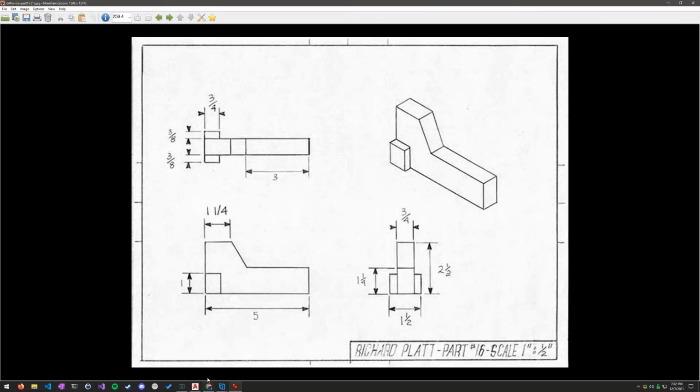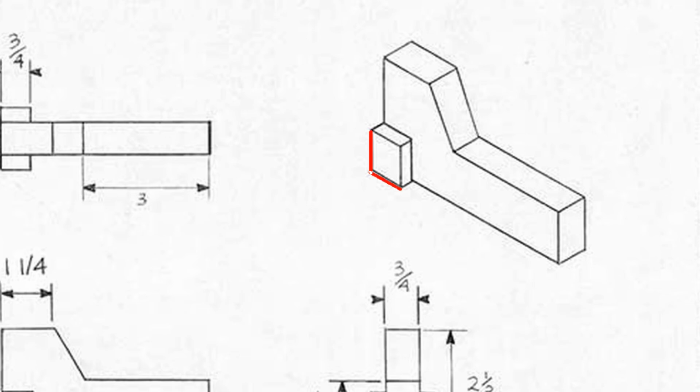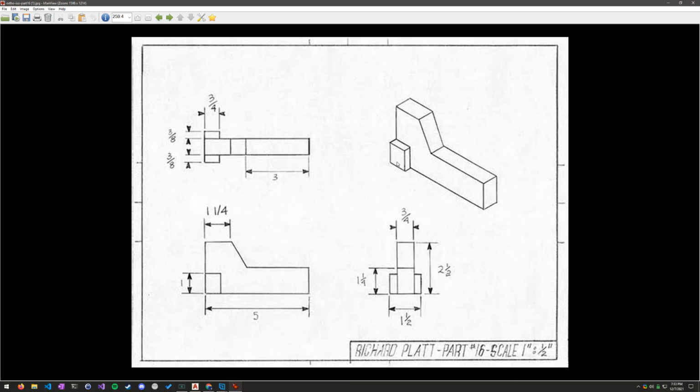Okay, so continuing on, we just did this. Now I'm going to go ahead and do these: 1, 2, 3. Notice that there isn't one going here, because that would make this look like what we call a wireframe, or like it was made out of glass, like we could see through it, but we can't. We're trying to imagine that this block is a solid block, either made out of wood or metal or whatever. It's solid. We can't see through it. So I'm going to go ahead and do those 3 lines now.